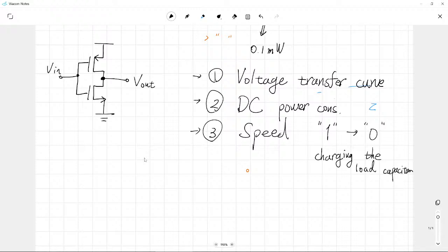So first one, voltage transfer curve. Let's just consider the case where we apply logical 1 to the input. Then the ideal case would be just logical 0. Now let's think about this one, the NMOSFET. Yes, it contributes just as before. It can provide a certain good channel.